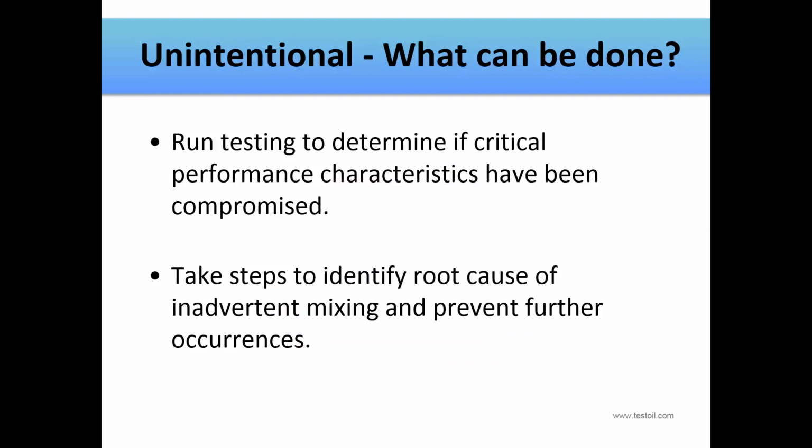For instance, if there was a new delivery of oil for a steam turbine and it was contaminated with a small amount of engine oil and it wasn't discovered until the oil had been added to the system, I would suggest testing the in-service oil that's actually in use in the machine for the critical characteristics as applicable to a steam turbine. So specifically, the ability to separate from water would be one, and rust prevention. If the lubricant meets the expectations, then an oil change might not be vital. However, the oil change might be warranted if the lubricant doesn't function as it was intended or requires.